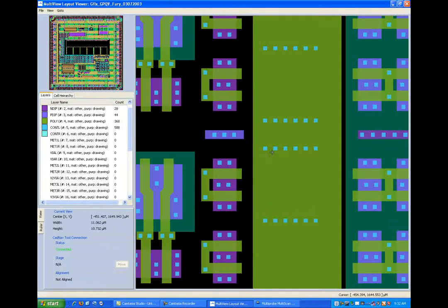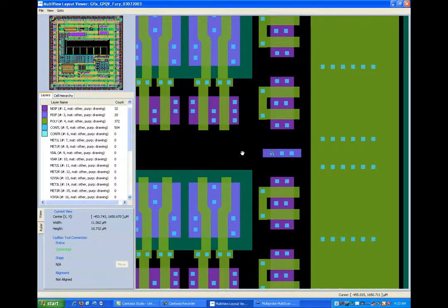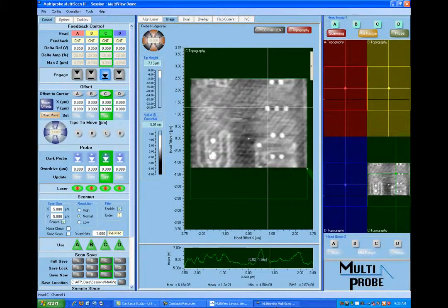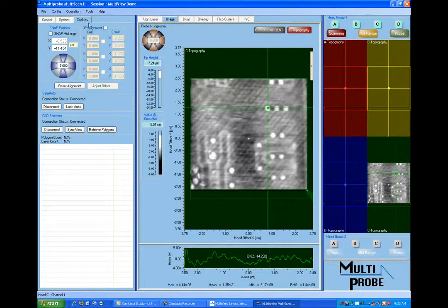We've placed the cursor on top of it in Multiscan, and we'll be placing the center of the view in Multiview in the same place. We can do that by right-clicking the point or just dragging the image around. We've actually started this a little bit out of order here. We've already picked our points, but we'll just tell Multiscan we're doing the 3-point alignment now.